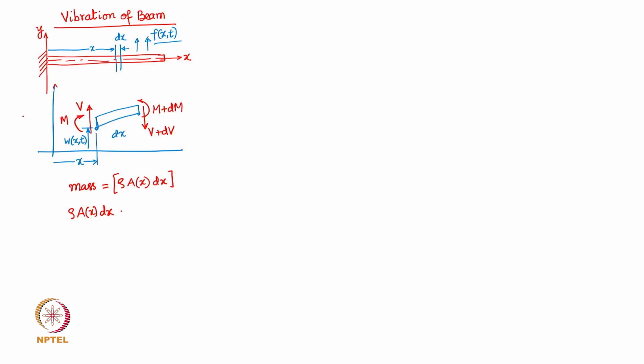So in this case, the lateral deflection and the vibratory displacement is w(x, t) at x point, which we can treat as the reference point, and then write the acceleration of this entire element to be the second partial derivative of w(x, t) with respect to t, as the acceleration of this infinitesimally small element.